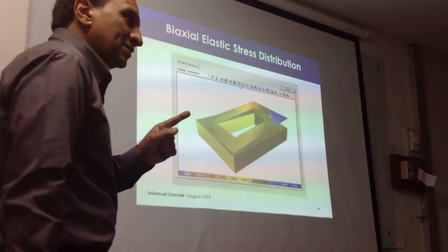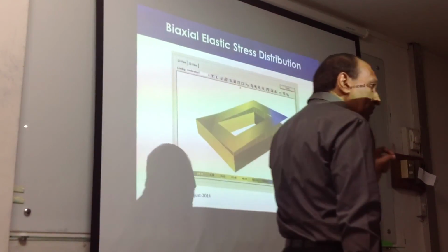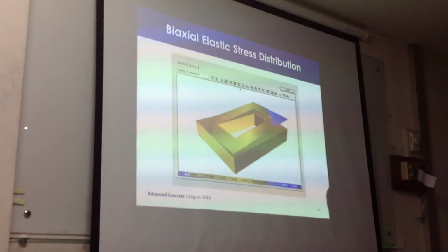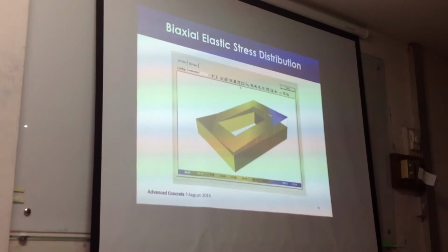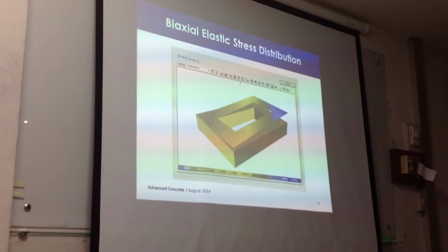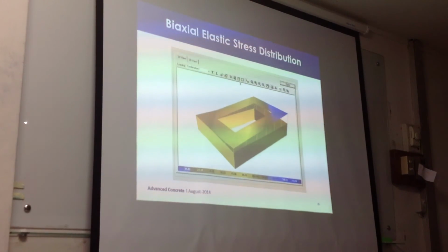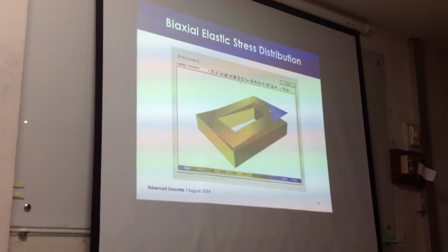And that is only existing, why? Because we force the strain to be a certain value, which is not true. We always assume, no matter how small or how big the moment is, that strain in concrete will be 0.003. Okay? How wrong is that? Because the moment may be very, very small and that strain may never be produced.